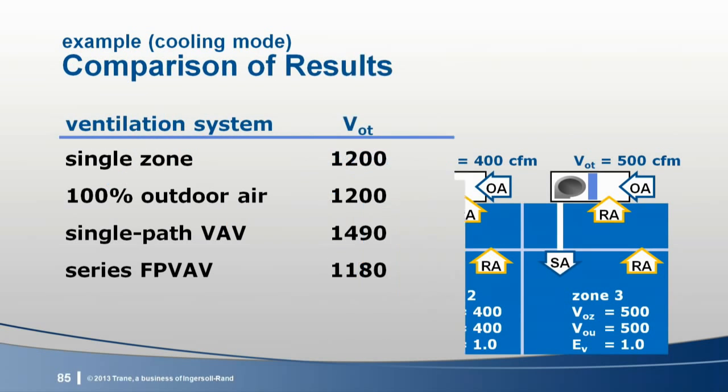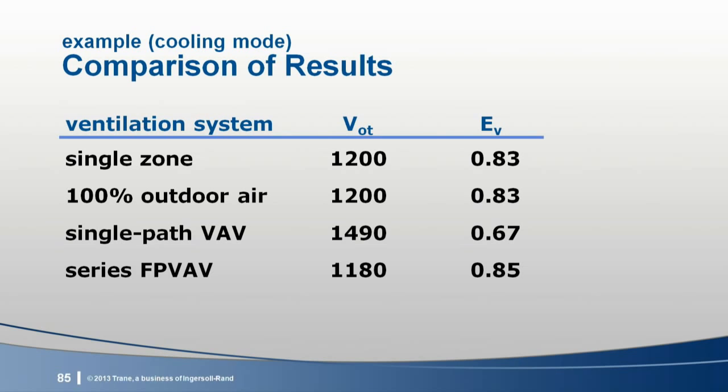So when comparing the performance of these different ventilation systems, you need to compare the calculated intake airflows, not system ventilation efficiency. Even though ventilation efficiency is typically not 100% for these other systems, it's not calculated as part of the ventilation rate procedure in ASHRAE 62.